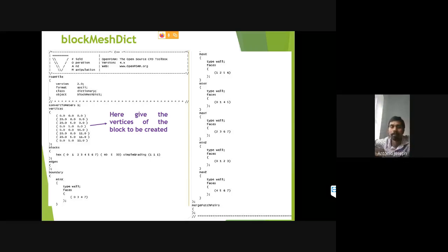For example, if I am dealing with a simple fluid flow problem which can be steady and having some low Reynolds number, then I can use simpleFoam. And if it has a higher Reynolds number, that may be a turbulent flow, but it is time independent, then again I can use simpleFoam. No problem in that. But suppose it's transient, that means it's unsteady, that changes with time.